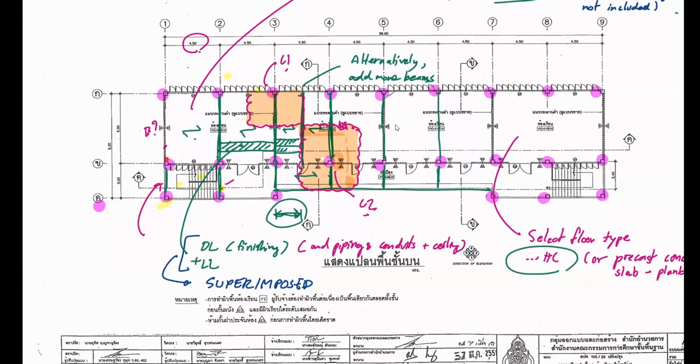Are you with me? Yes. This beam will carry half the floor, but it will carry the wall. Okay. Actually, we have 3 classrooms, so you may include the wall on this beam, so it's going to be heavy. So now you have 3 loading criteria for this beam. Okay, this beam, half the floor and the wall.